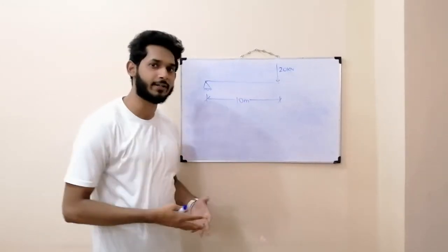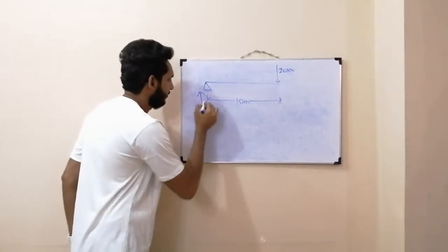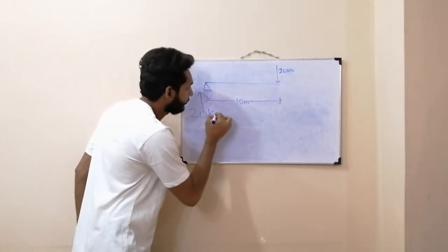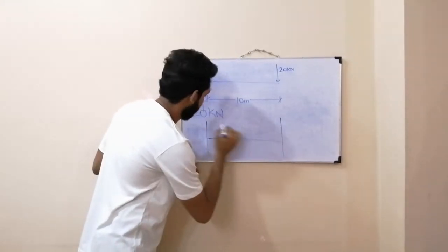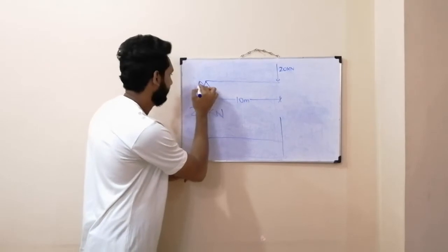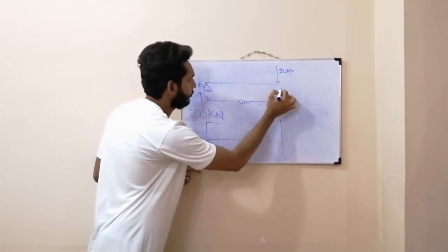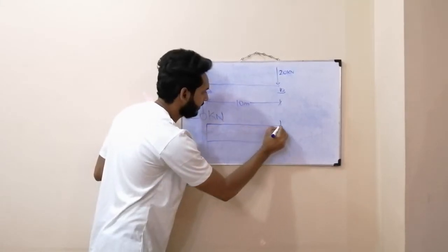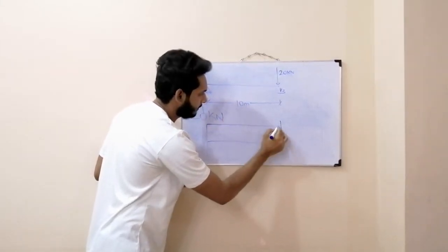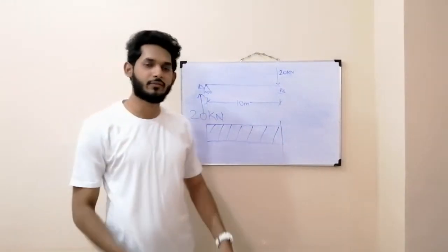we suddenly jump right into it and draw shear and find out the reactions like, hey, let's say this is the 20 kilonewton upward reaction, and the shear force would be at point A, there is an upward loading of 20, and then from point A to point B, there is no force in between, so the shear force remains constant. On reaching point B, the shear force comes downward. And we say to the employer that, hey, look, I have drawn the shear force diagram.